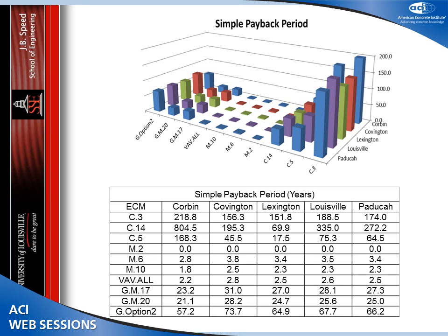We did a similar analysis, again, to present this graphically, and what we're looking for is shorter bars this time. The large bars represent longer payback periods, and you can see that they do vary with climate, even within the subclimate we're dealing with in climate zone 4, by the way, in the reduced ASHRAE climate zone numbers.